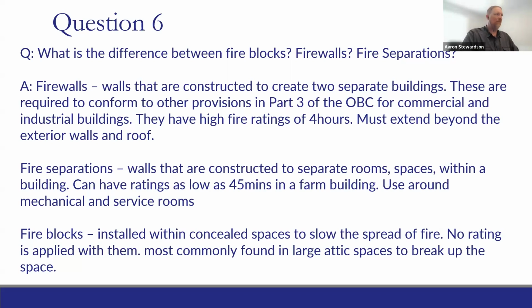The fire block's not supposed to stop like a fire separation or a fire wall. It's just supposed to slow the spread of fire to allow for easier access for the fire department to control where the fire is, right? The spaces for attics as well has been increased. So it used to be in some larger farm buildings, we had to split the attic two ways. Now we're actually in only into one way. It's over 100 feet. It doesn't matter the width of the building. So that is something that the province has increased the size of to allow for the spaces in attics of farm buildings.